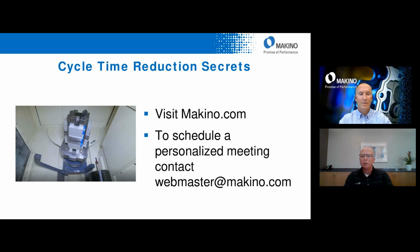We like to execute that M code at the beginning of the cutter path of your machining program to look at all the tools in your magazine. So the format is M36, and then the next lines are the tools you want to check the status of. It's looking to see if the tool is in the magazine, if it's available for use, and if the status of the tool is not in an alarm status.